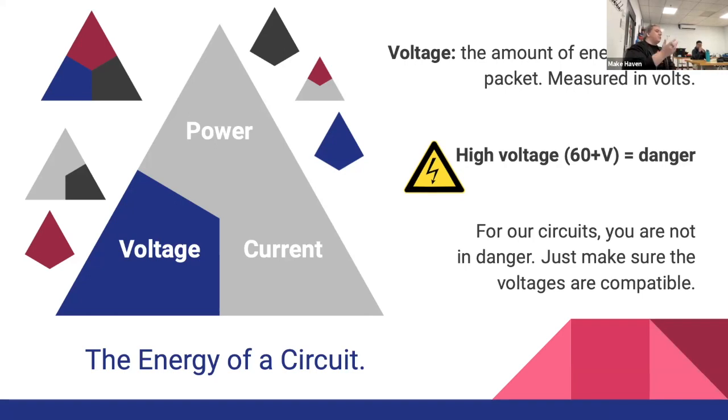Whereas when you plug something into the wall, that voltage is 120 volts here in the United States, and that's a little bit more dangerous. The reason higher voltages are dangerous is because they can travel further through your body and interact with your body systems. That's really what makes electricity dangerous. Also burns. So the high level takeaway is that nothing we're working with in our soldering projects is at a high voltage.